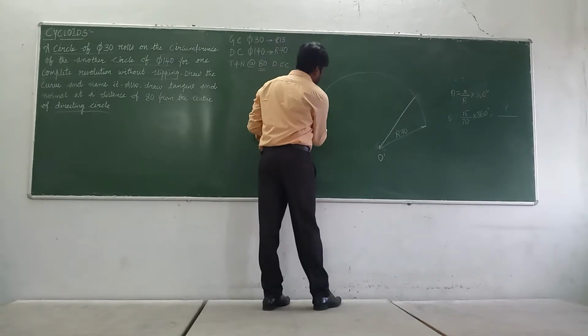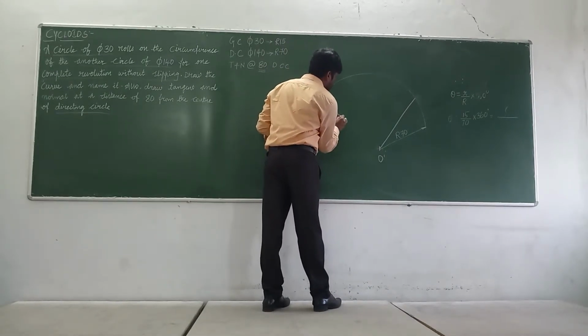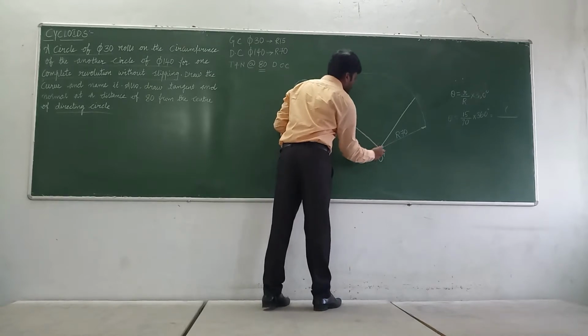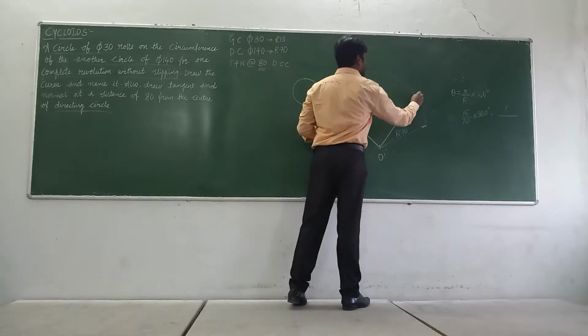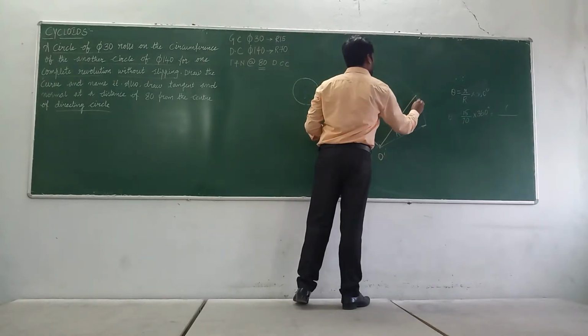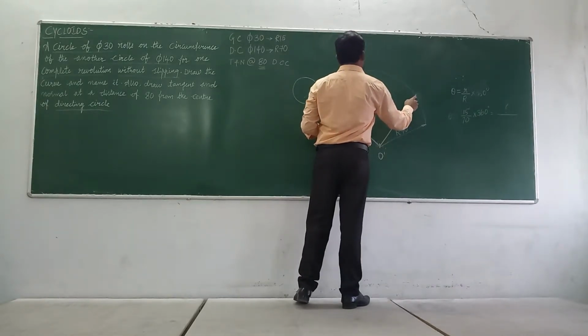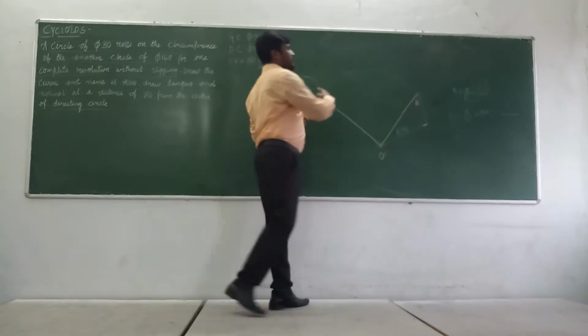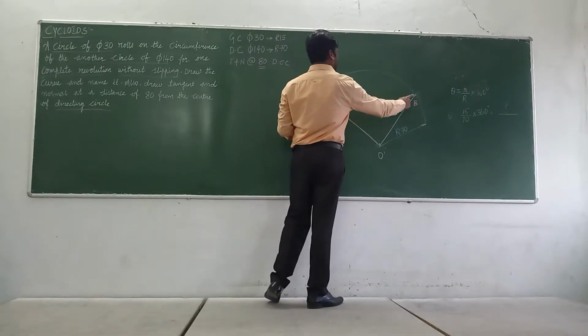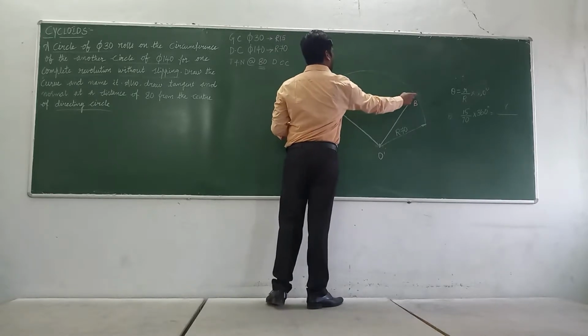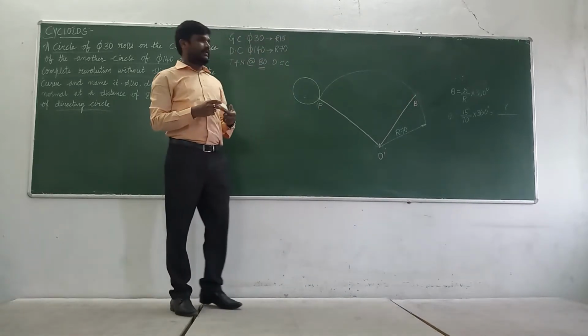This is my path where I am going to trace my cycloidal curve within this limit. That means from here to here. So this is my point B. B is on the directing circle arc. Now, from where I am going to start, the initial point, and where I am going to end my revolution or rotation of the circle.